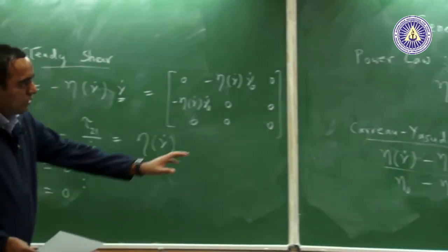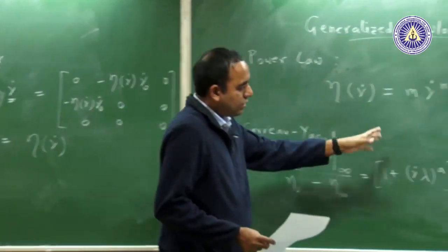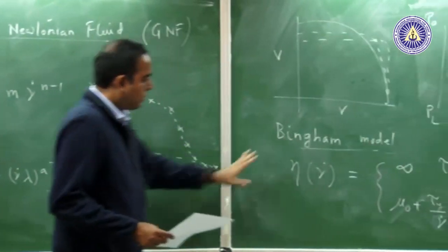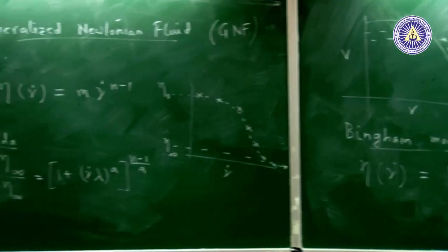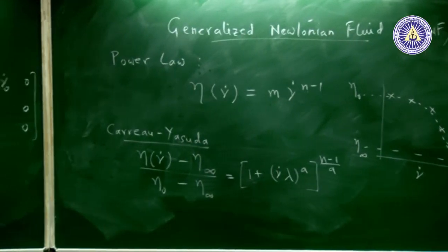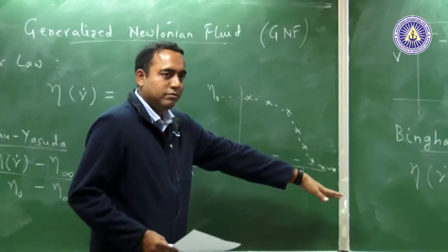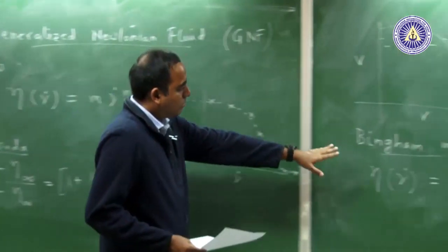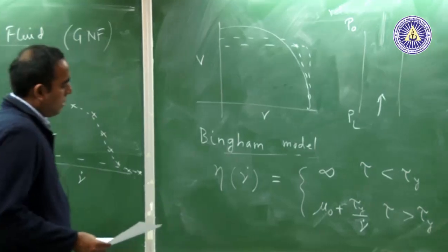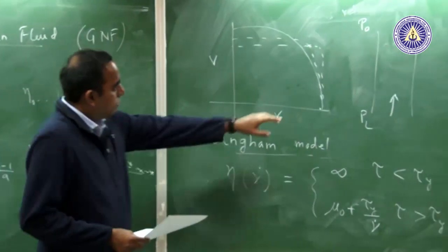Now, notice that all of these have some kind of empirical things built in, there are no first principles going on. It is just that I have to correct the viscosity for steady shear. So, I correct it in various ways depending on what data I have. So, one of the more classic examples of Bingham model flow is through a pipe.